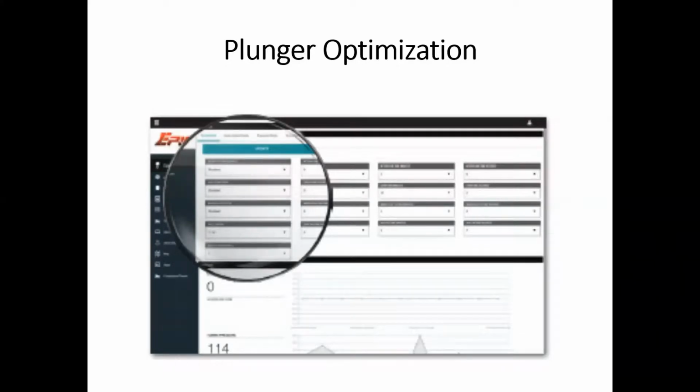The ideal travel time for a conventional plunger is 650 to 750 feet per minute. You do not want to exceed about 800 feet per minute, or it could cause serious damage to the plunger or surface equipment. This ensures that your gas rate is above critical rate, you're bringing fluid up, and the plunger is not impacting the lubricator too hard.